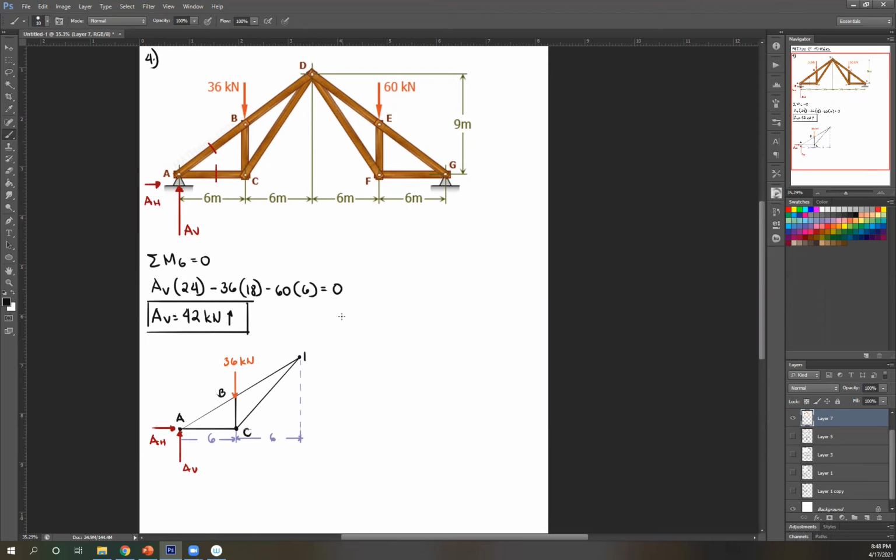So it's similar to what we did earlier. We're taking moment about the hinges. So this is also a hinge. Alright, let's start. AH, rotate that about D. That's counterclockwise, so negative AH. Perpendicular distance is this height. Is it given? Yes, it's 9. So this is 9. So negative AH times 9.